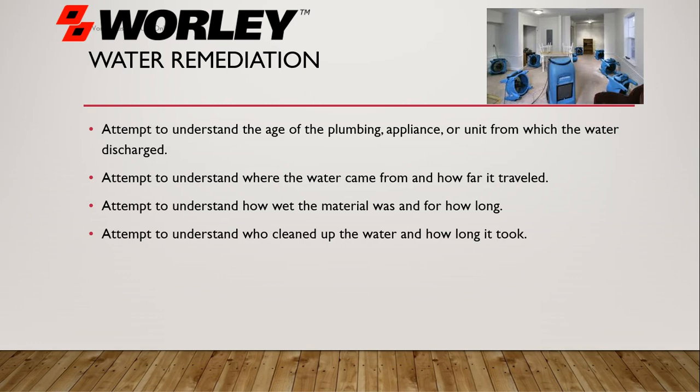Attempt to understand the age of the plumbing, the appliance, or the unit from which the water was discharged. Attempt to understand where the water came from and how far it traveled. How deep was the water? Where did it go? Where did it flow? Attempt to understand the wet material and how long it was wet.